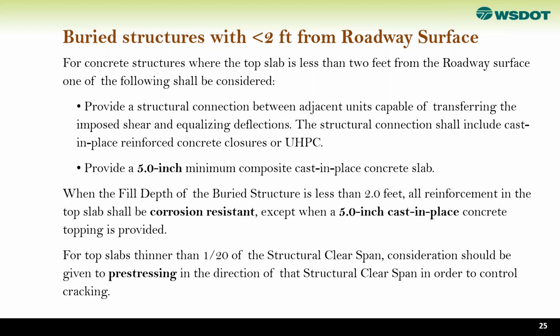And the other case, which is also our typical practice for precast members subjected to traffic, is using a 5 inches minimum composite cast-in-place concrete on top of that. If the fill depth again is less than 2 feet, we require corrosion resistant reinforcement for that upper portion, unless you are using the cast-in-place concrete on top, in which case the buried structure doesn't need to meet the corrosion resistance, because the CIP topping will provide the corrosion resistance.